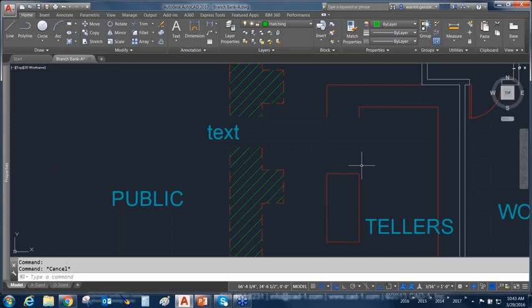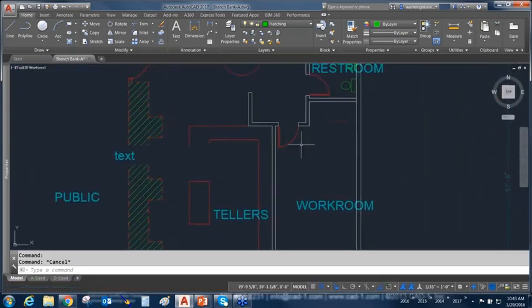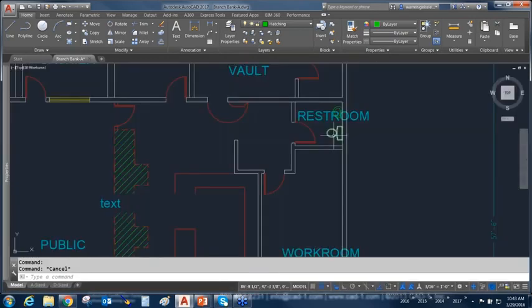Now, as far as different states of the dynamic blocks, that could be a very interesting proposal. Always remember that the annotative scaling will react to your grips and how the grips work, and that grip position is going to be different on a scale-by-scale basis. If you introduce the multiple grips and the sizing grips on a scale-by-scale basis of an annotative object, you may be able to do exactly what I'm showing you here.